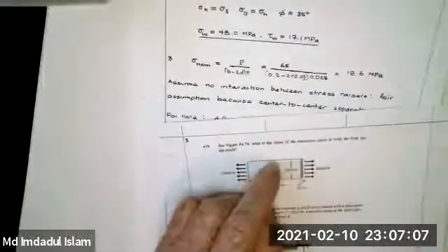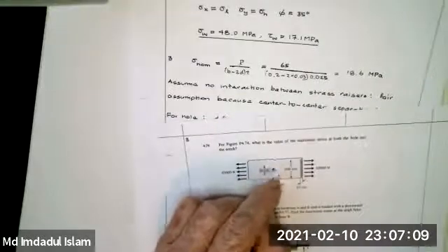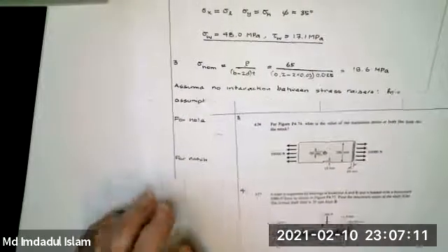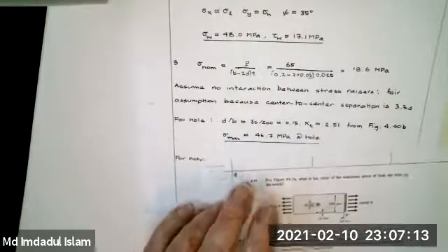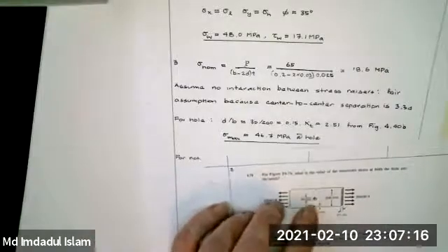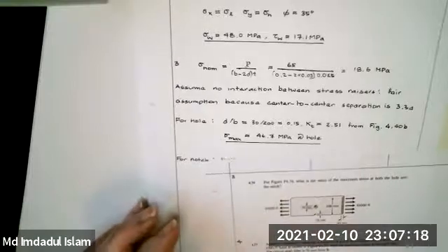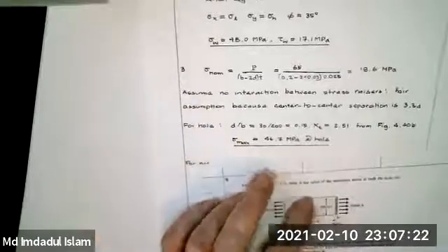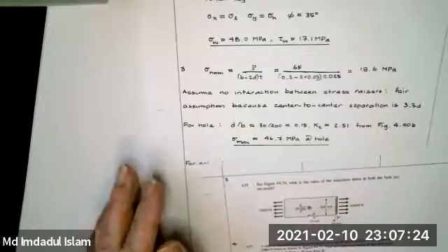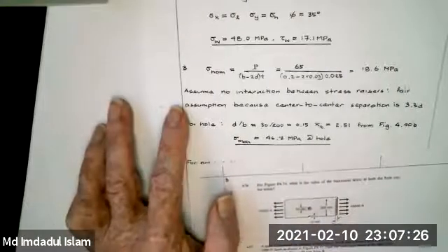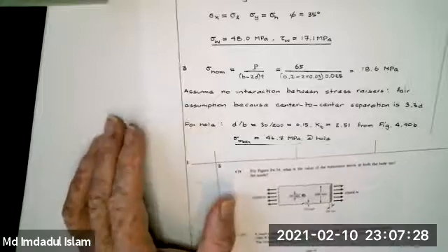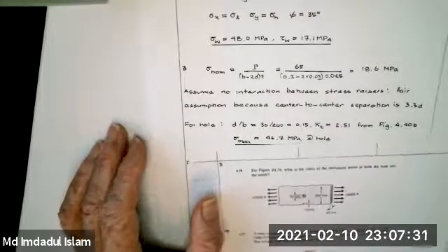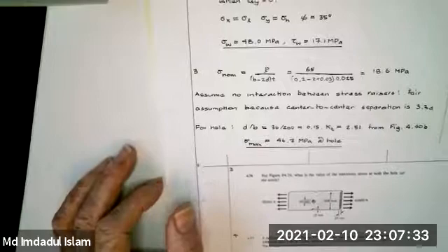So we didn't exclude the hole. We just took the total thing. If they started to get closer, one way you could attempt to track interaction between the two stress concentrations would be to do what you're saying. Once you make this assumption, then you just ignore the hole. But if you start to be worried about this, let's suppose it gets down to about 2 diameters, then doing what you're saying is a reasonable thing to do.